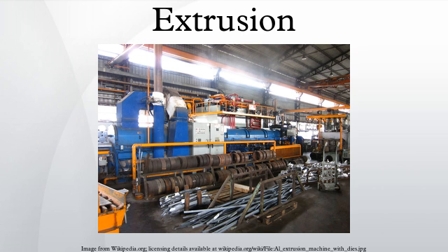Materials. Metals that are commonly extruded include: aluminium, which is the most commonly extruded material. Aluminium can be hot or cold extruded. If it is hot extruded it is heated to 575 to 1100 degrees Fahrenheit. Examples of products include profiles for tracks, frames, rails, mullions, and heat sinks. Brass is used to extrude corrosion-free rods, automobile parts, pipe fittings, engineering parts. Copper: pipe, wire, rods, bars, tubes, and welding electrodes.